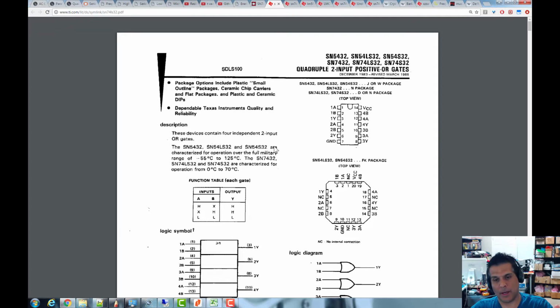So again, say we're building a computer and a circuit, and we've got a microcontroller, like a Raspberry Pi or an Arduino or whatever, and we've got some circuit. We know that the processor is going so fast and we want to do this computation electronically. We look at the propagation delays, add them all up, and say, wait a minute, we won't be able to do this, because when you add all these propagation delays up, it's going to take too long for how fast this processor is going. We've got to do it faster. Well, wait a minute. Can we turn our ORs to ANDs or ANDs to ORs? Right? And yes, we can, with DeMorgan's law.